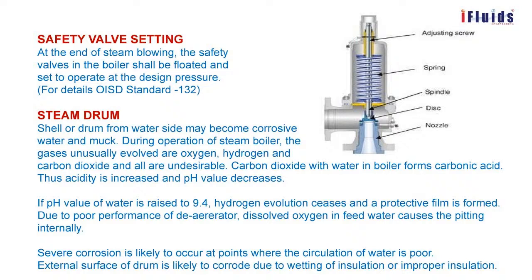Once the safety valve is set, it has to be tested in the field itself. That is, with the safety valve in place, the pressure will be increased to the set pressure and that should be checked for any release or not. If release has taken place, it is okay. Otherwise, it needs to be tested again, repeatedly we have to test it.